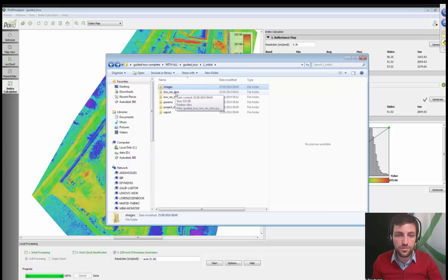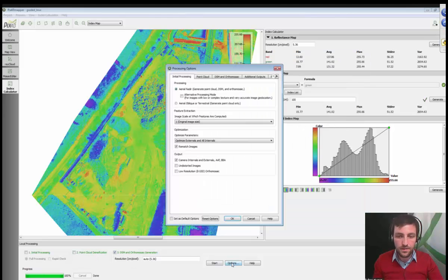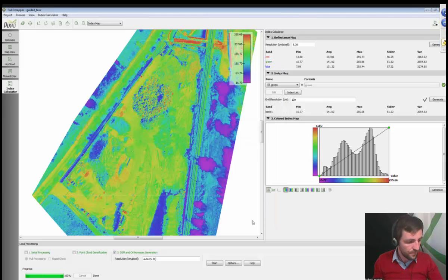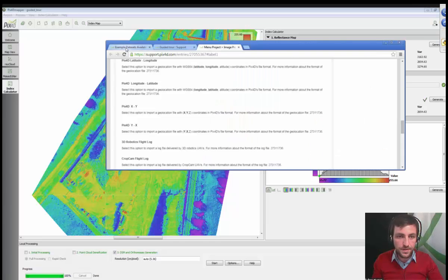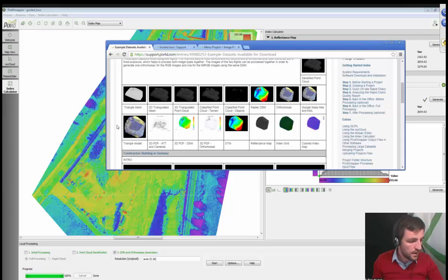It is also possible to generate a low-res DSM and mosaic directly from the initial start of the processing, without doing the densification and DSM. This is available when you check this low-resolution Mosaic option. There is also a possibility to generate directly classifying the point clouds.